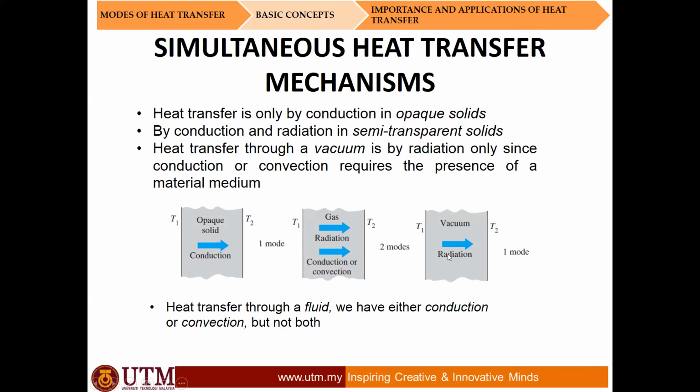In a vacuum, only radiation. That is what simultaneous means: two mechanisms occurring at the same time. Heat transfer through a fluid can be either conduction or convection, but not both. If there is motion of the fluid, the heat transfer is convection. If there is no motion of the fluid, the heat transfer is conduction.